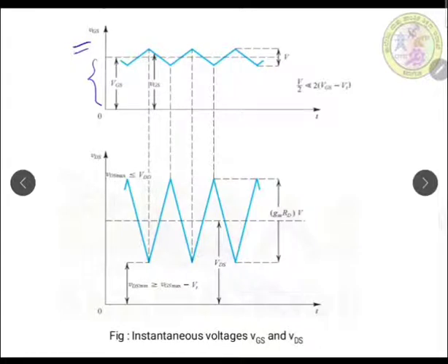Okay, and the condition for the small signal is, if its peak-to-peak amplitude is V, then V/2 should be very much less than 2 times (VGS minus VT). This condition we have seen while deriving the signal current in the drain terminal topic. So the first picture represents the instantaneous VGS voltage.